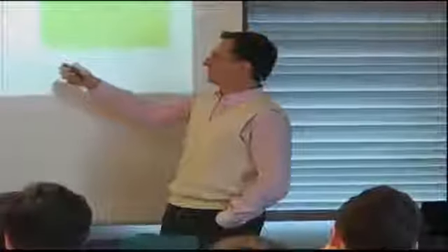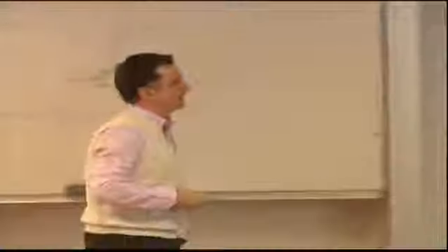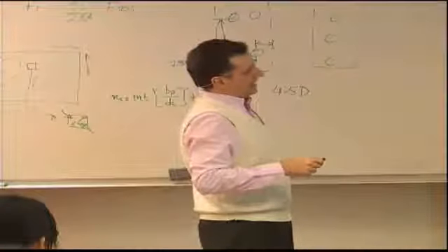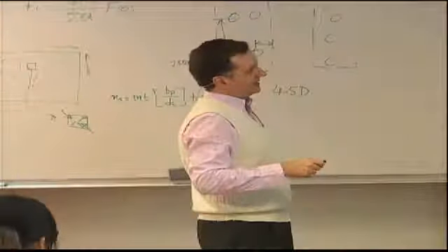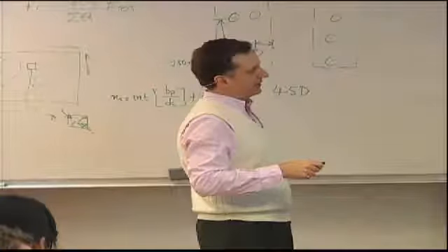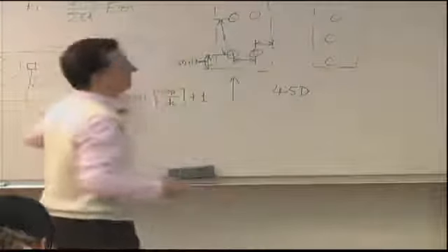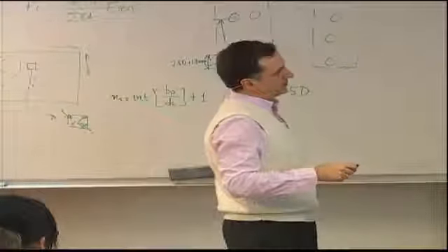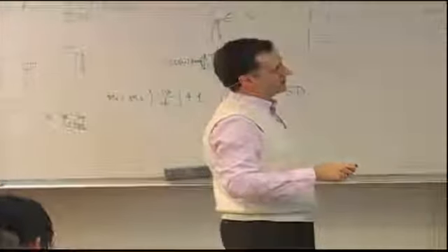That's because the A matrix is EA per unit width, and the sum of the EAs gives us the total equivalent EA. The A of the stiffeners is the number of stiffeners, NS, times the A contribution for a single stiffener.